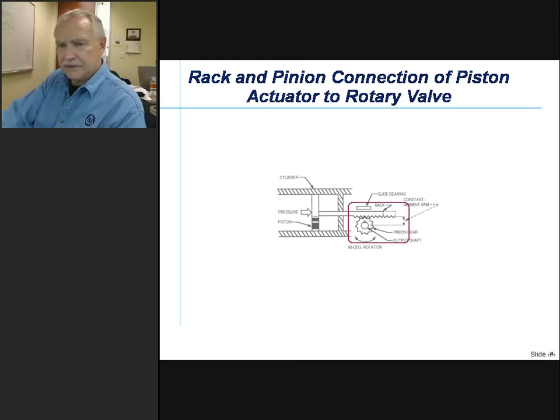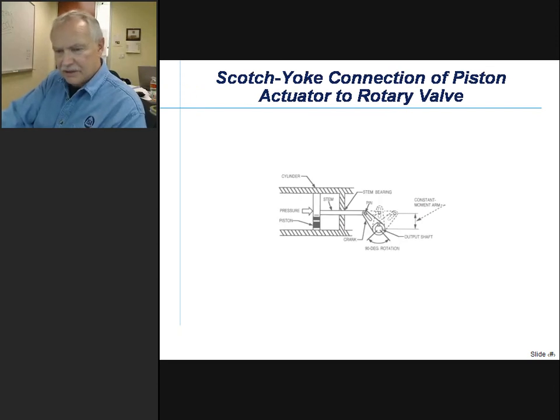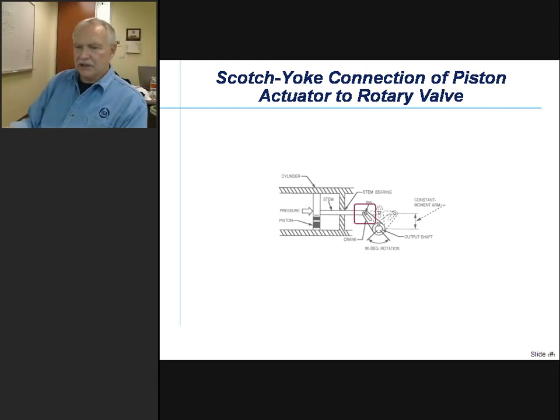The Scotch yoke actuator has particular problems, and again, this pin here and the slot create quite a bit of backlash. So not shown here is the preferred solution, which is a splined shaft and a diaphragm actuator with rotary motion that eliminates the need for this translation and linkages or slots and teeth that we see in these previous slides.